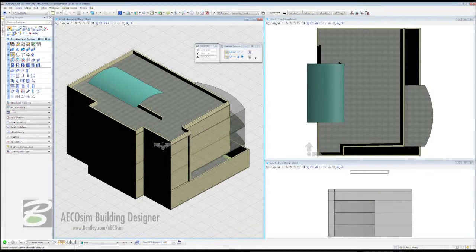We come to our third row down, to our mitered finish here. We're going to choose this one like that, and this wall like that. And then the original walls that we placed down, we'll need to have those connected as a T. So we're going to choose this existing wall and this new section here, and this one across here. Okay, cleaned up, it's professional, it does exactly what it should be required to do.